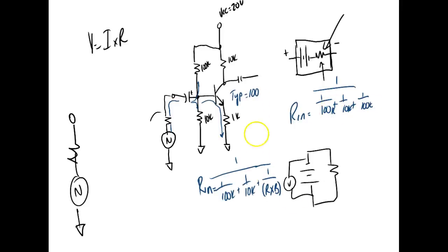So what I did in my head is I took R, which is this, and multiplied by beta. And what's my internal resistance now? What does my source see? So somebody work that out for me. Shouldn't take very long, guys. Y'all should have done all these in DC, right? So it'd be 100 times 10 to the third reciprocal plus 10 times 10 to the third reciprocal plus 100 again times 10 to the third reciprocal equals reciprocal.